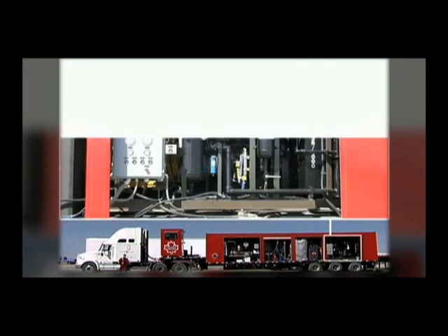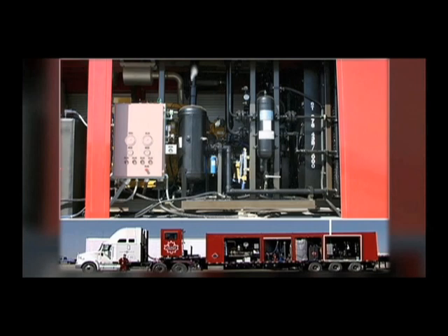In the final stage, the nitrogen passes a flow meter and fills a nitrogen receiver before entering a series of pressure boosters and heat exchanger, all of which builds the discharge pressure to 4000 psig or 27.6 megapascals. Nitrogen flow is controlled by a combination of inlet pressure variations and bypassing the final discharge back into the first stage inlet through a flow control valve.